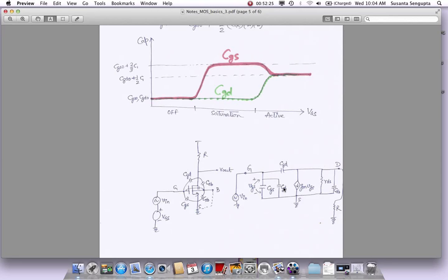What we do is, wherever we want to extend the speed. Let's say the circuitry doesn't have the speed and we want to extend it, and we have these parasitic capacitances, let's say a CGS, that we cannot avoid. What we can do is put an inductor in parallel with it, either in parallel or in series. Most of the time you put it in parallel. Whenever you have an L in parallel with a C, that LC circuitry will resonate. The inductor and the capacitor in parallel form an LC resonant tank. And when it resonates, it becomes open circuit. It open circuits the capacitance.